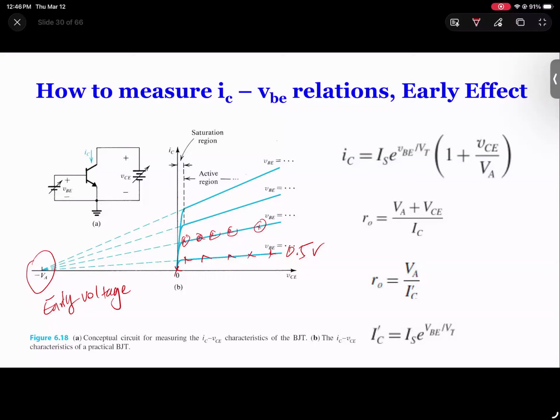Another thing I want to say is, even though the circuit shows this, it's dangerous if you do it yourself, like in a laboratory at home. Why? Because the current is very sensitive to those voltages. Remember what we were talking about, VBE is 0.7. It's really around 0.7. If it's below, that's okay, because the circuit is not going to conduct so much current.